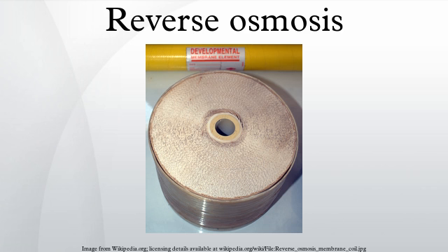This varies with the salinity of the feed water and the system design parameters, typically 20% for small seawater systems, 40% for larger seawater systems, and 80% for brackish water. The concentrate flow is typically only 3 bar/50 psi less than the feed pressure, and thus still carries much of the high-pressure pump input energy.